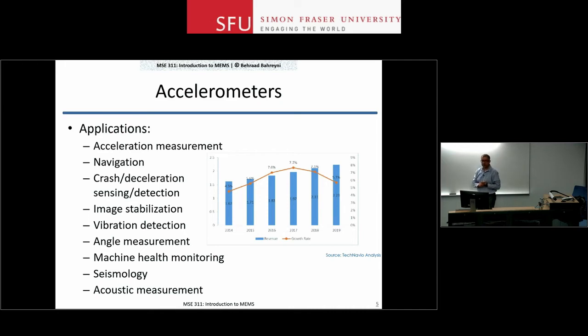Seismology is an up-and-coming application area for MEMS accelerometers. This is where we want to listen to or detect vibrations of the Earth, right? These are usually low frequency and small in amplitude. You're talking about micro-g level signals here that are below 50 hertz in the vast majority of cases. Measurement of low amplitude, low frequency signals is a tricky business, but MEMS devices are getting so good that they can do that kind of measurement.